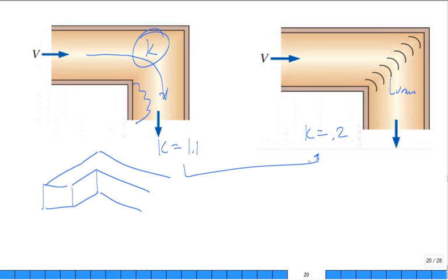Most homeowners don't know. Once it's sealed up, taped up, and in the attic, and it's hot in the attic, you're not going up there. Most homeowners don't even know what carries the air in the attic. But it would make a significant improvement. If you're a design engineer working on a building, maybe you specify that the contractor put those in to help reduce the pressure drop in duct flows. I had one of these in a house. I went up in the attic and looked, wondering why a room wasn't getting airflow. The duct size was big enough, it's just that the 90-degree kink added so much equivalent length that it was choking the flow.